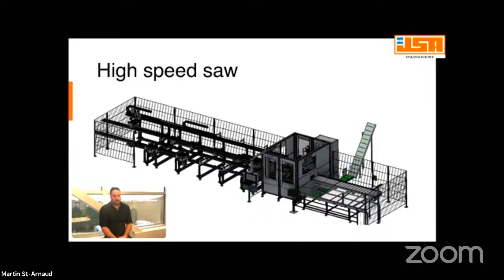So two different types of saw, where you're going to be cutting either one bar at a time, which is going to bring you to your goal of 400 squares on a shift. Or if you're cutting 2 bars at a time, you're going to be able to feed 2 welders or 1 double stack welder for somewhere around 800 squares in 1 8-hour shift. So as I said, there's been a lot of advancement in those saws' technology. So just keep an eye on those if the saw is your bottleneck at this point.